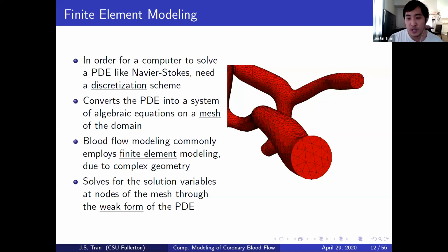But in order to actually simulate this, we need a method to discretize it. For 417, we've used the finite difference method and finite volume, and in 410 we use finite element. The method I typically use for my simulation is finite element, because finite element methods really shine for applications where the geometry is very complex and awkward. With very patient-specific geometries, you're not going to be dealing with nice cylinders or squares or rectangles, so you need something that can adapt to that geometry. The finite element methodology really helps us out for that.